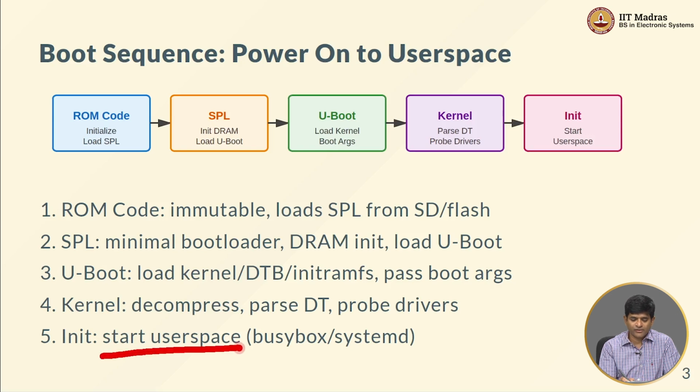That is what we call user space. So this is essentially the sequence of steps that happen from the time you switch on your machine to the point that it is actually interactive. You can probably type commands, assuming that init was something like BusyBox, which allows for interaction. If it's not, and it's a completely embedded system, you can also have an init which just does one particular task and nothing else.